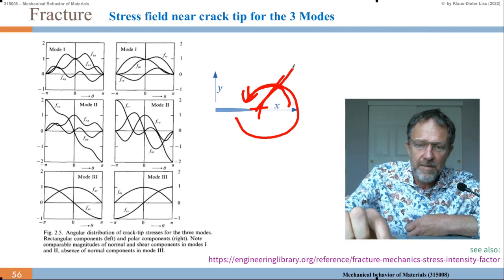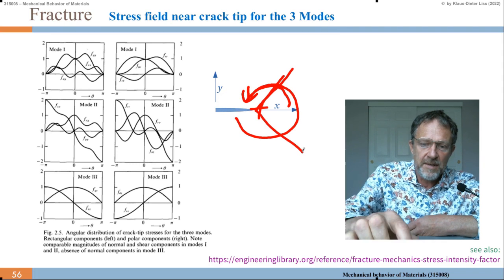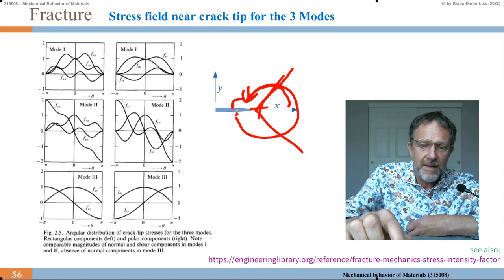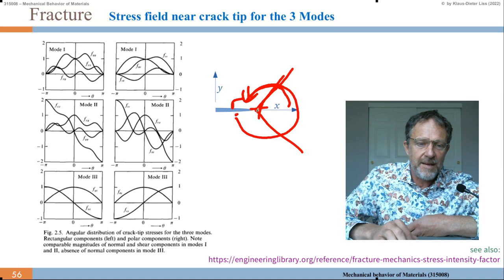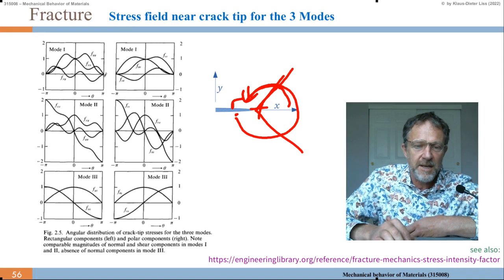That means the sigma yy becomes maximum in those direction. We said already when we are plus and minus pi, it has to be the free surface, this little blue thing here, and the free surface has the stress boundary condition 0. So that was our boundary condition.